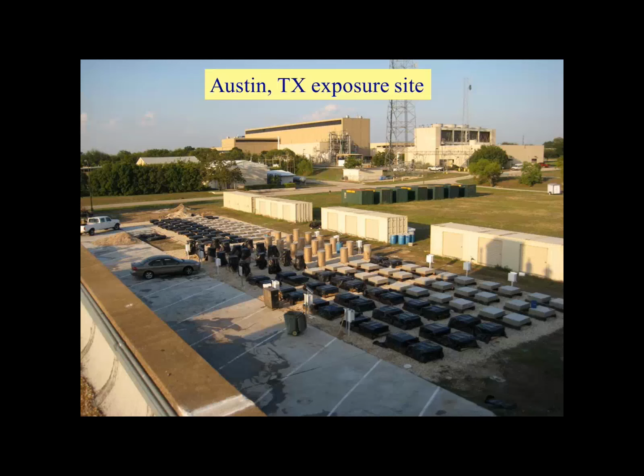A higher performance concrete will do better with regard to ASR, but it will not be resistant to ASR. What we've seen is it often will delay ASR because of the lower permeability, but ultimately, if the alkali loading inside the concrete is high enough, you still will get ASR. It might just be delayed for some period of time, but it certainly isn't the answer by itself.